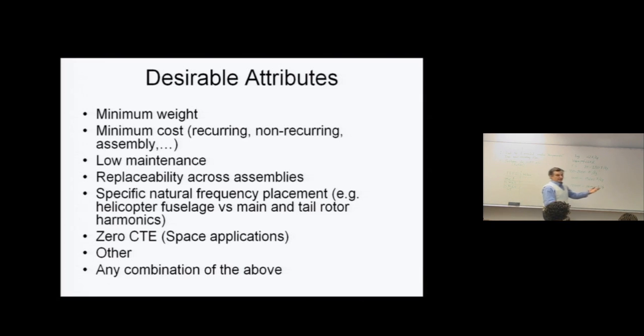So they give incentives to the engineers, and they say for every kilogram, basically we pay you the amount that the customer is willing to pay. So I was in a program which was at 15,000 euros per kilogram of weight saved. Some of the stress engineers had been smart enough to have a little bit of extra safety factors in their designs, a slightly higher thickness, because the loads go up, because of whatever, anticipating and not wanting to have to go and change everything at the last minute. So it wasn't highly optimized, but it was optimized.